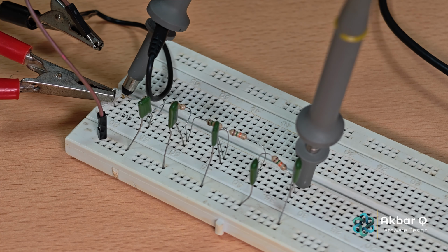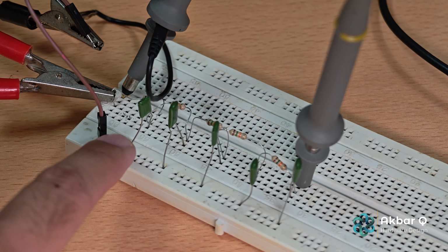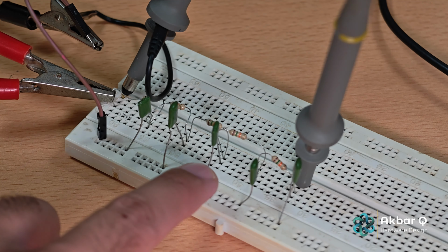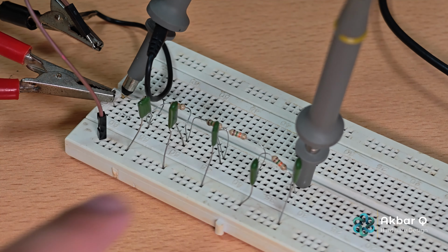A brick wall filter is a type of filter which completely eliminates frequencies with a sharp decline. Basically, the more low pass filters you have, the closer you get to an ideal brick wall filter. In this case, we have gone for a fifth order filter. That means first order, second order, third order, fourth order, fifth order. So 5 sets of low pass filters combine to get a fifth order filter. We can go on to a 7th order filter, 9th order filter, 12th order filter, and so on.